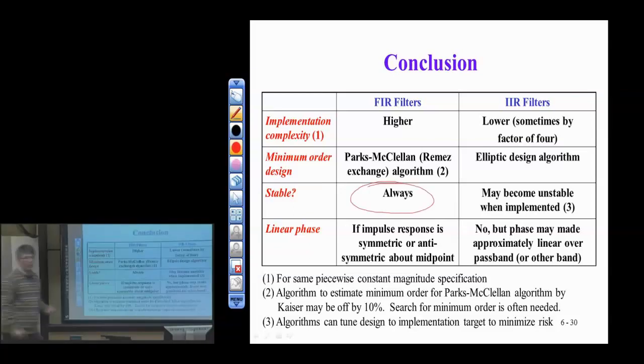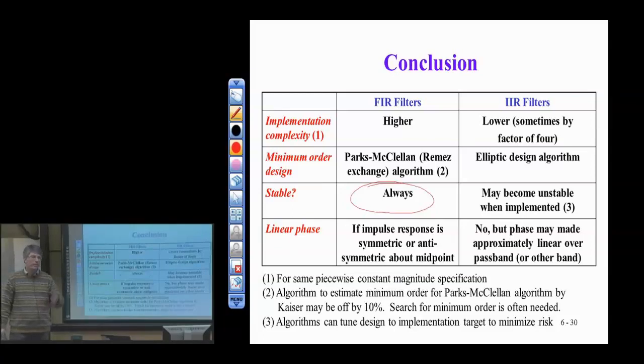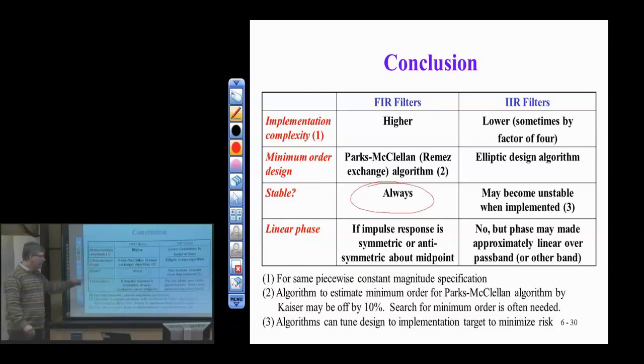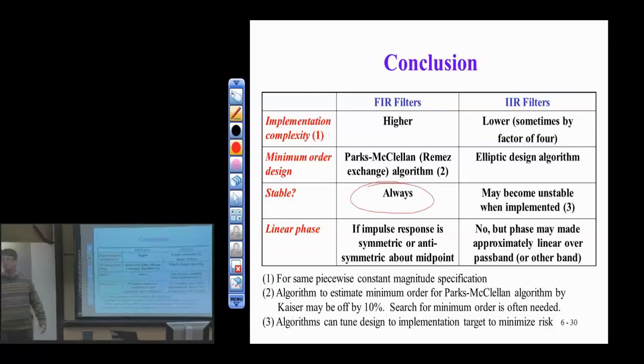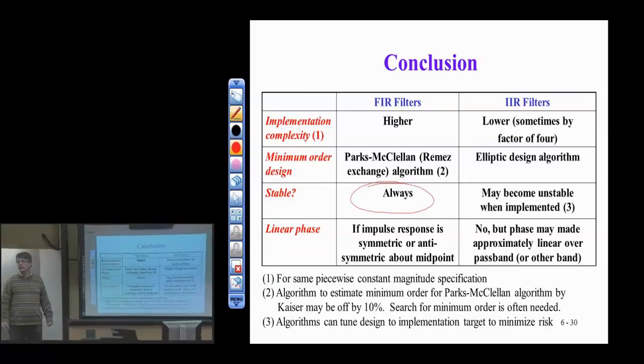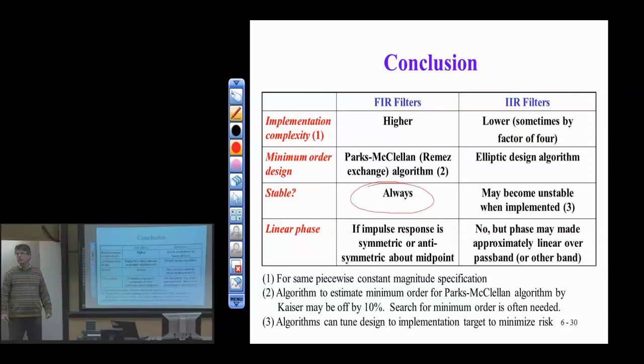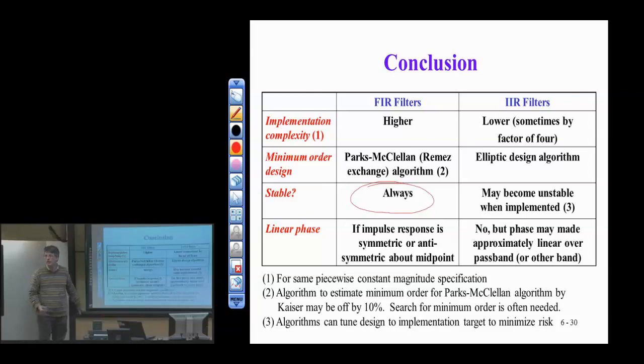The FIR filter is always BIBO stable, no matter how you implement it: 3-bit coefficients, 3-bit input, 3-bit output. Even with 1 bit, you could just do sign, and it still would be BIBO stable. It's amazing. Is that why it was impressive that someone designed the 30th order IIR filter? Yes. The stability is so. We had a presenter earlier this semester on the 30th order, and that was all biquads. It was done very carefully. But it's pretty amazing to get a 30th order IIR filter to work in, I think it was 32-bit integer arithmetic. Pretty amazing stuff, really.